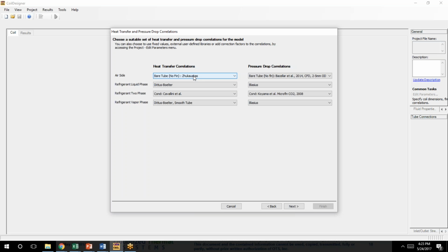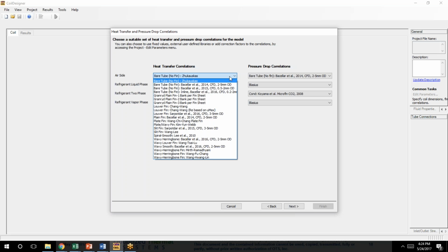So as we covered before in the first webinar, the airside performance, airside heat transfer is really fundamental in predicting overall heat transfer performance. It's definitely the dominant resistance in most cases. So it's crucial that we get the airside heat transfer coefficient accurately predicted. So we need to predict airside heat transfer coefficient for a louver fin, which is what we selected. So we need to select correlations for a louver fin. And we can see that there are several correlations available in the literature.